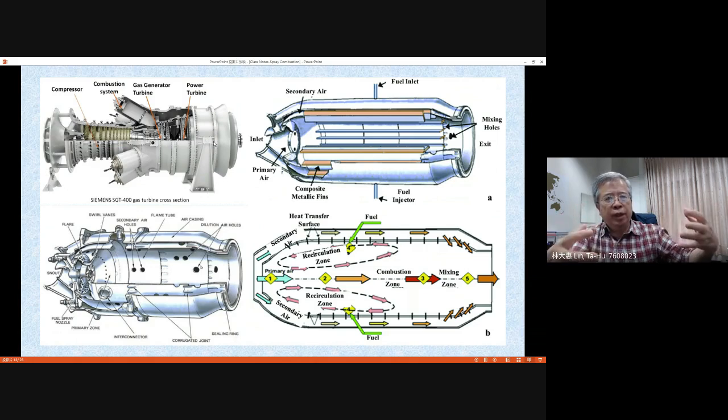That means the gasification and the mixing go to the optimal situation. In this situation, the burning is very strong, and temperature will increase to a high level, higher than the temperature threshold for the thermal NOx formation. Therefore, some designs to prevent this enhancement of thermal NOx are required for gas turbine combustion.